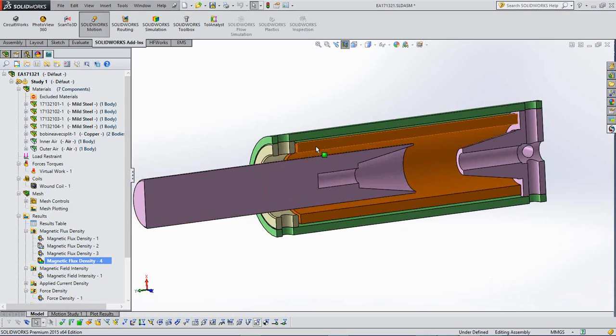And what's really happening as I pass a current through this coil, it generates a magnetic field, and this magnetic field exerts a force on this plunger, which is a ferromagnetic part, actually some kind of a mild steel or iron. So this force hopefully is going to push this plunger inside and help it to close the circuit.